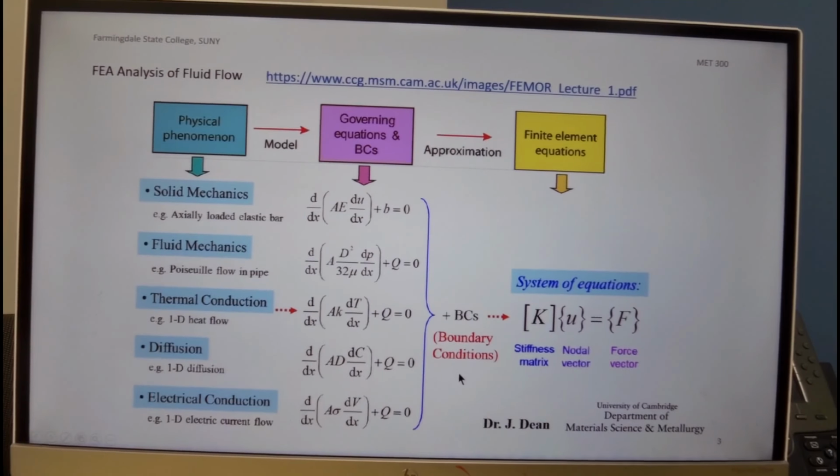The finite element method uses the boundary conditions, embeds them within the so-called strong formulation, and converts it into a weak formulation, which are algebraic equations that relate nodal values of the unknown variable to nodal force function at the continuum, related by the parameters that describe the phenomena.